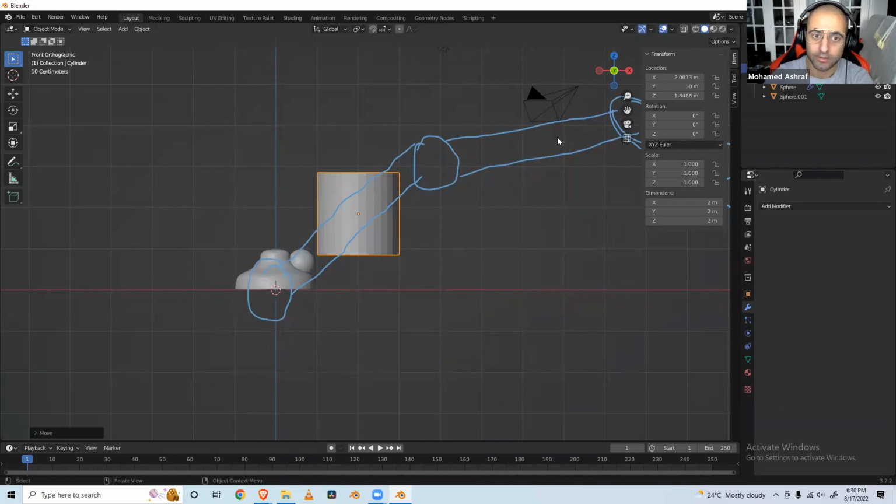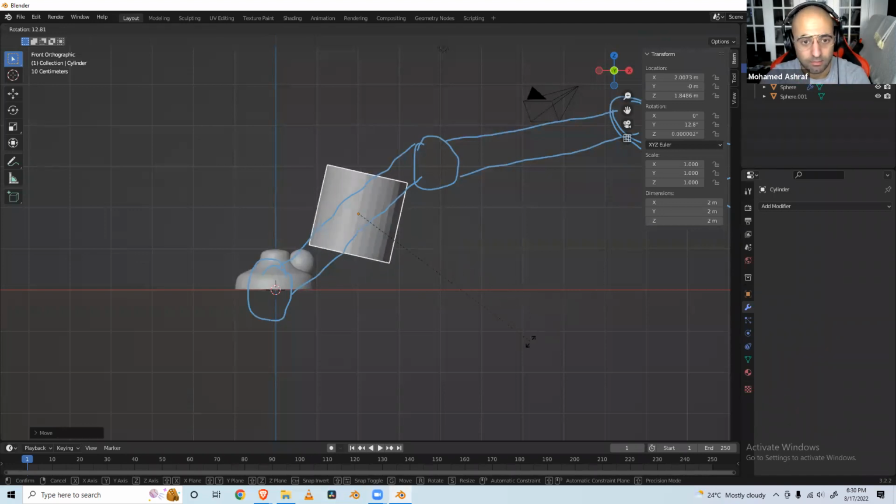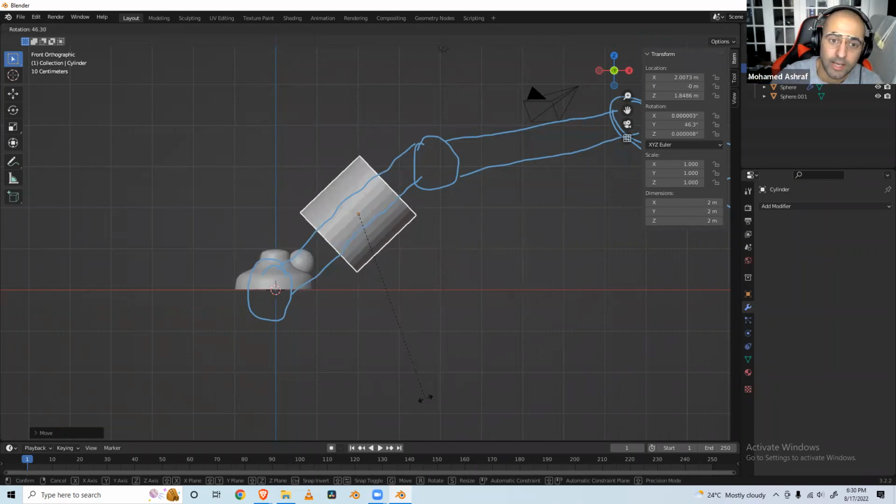Next we can rotate, since I wanted to take kind of this angle. We can rotate using the transform tab, or by pressing R. If I press R, the cursor automatically changes to indicate that you are in rotation mode, and it gives you an idea. You can see on the rotation tab the number for rotation along the y-axis. Maybe I can give it a clean 45 degrees.